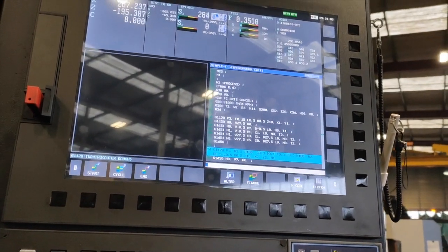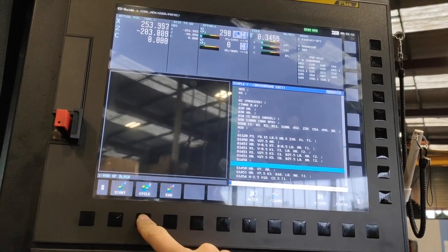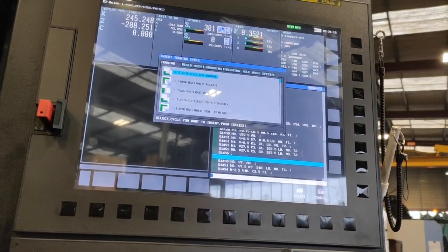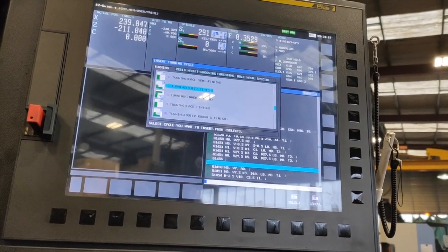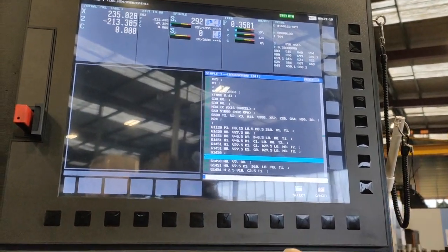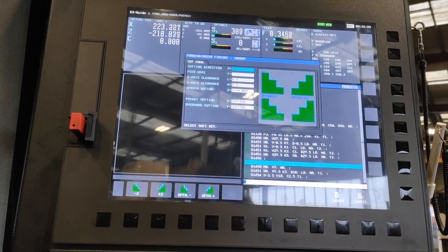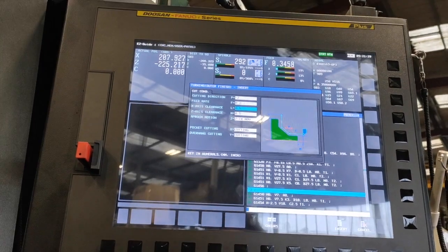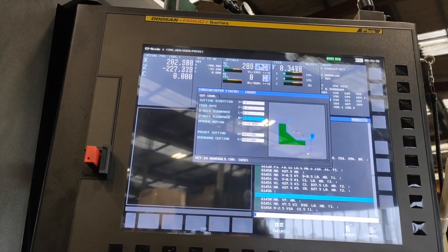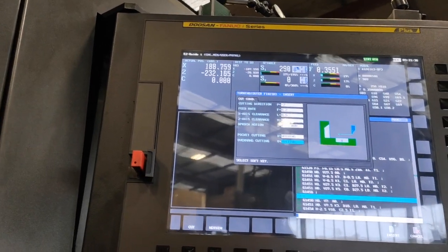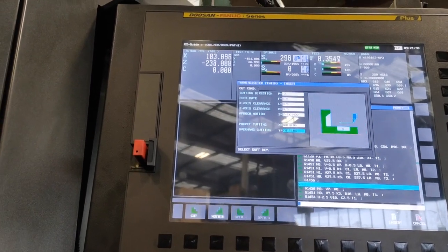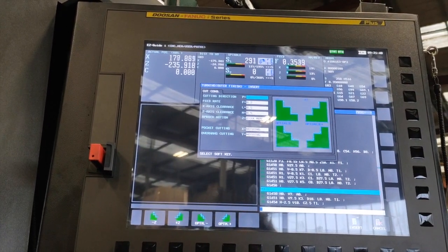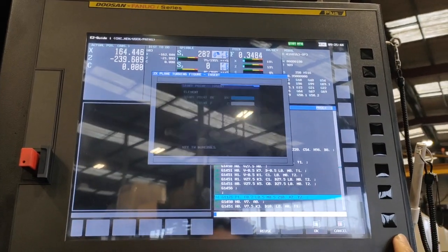So we can delete that one. We are going to cycle again, and then look for our outer finish. Select, same cutting direction, going minus. So our feed is, say, 0.2, clearance on X, 0.5 on Z, pocket cutting, nothing, and then insert, then cancel.